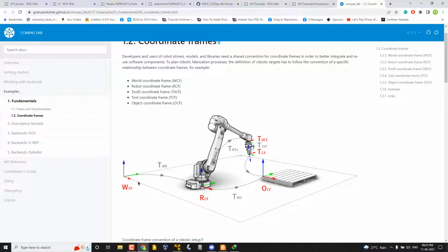All these broadcasts you can find from the TF topic. Basically the TF topic is an aggregate of all the transformations that you are broadcasting, and from this TF tree we can listen to any transform. Some nodes are broadcasting the transform, some nodes are listening to it.